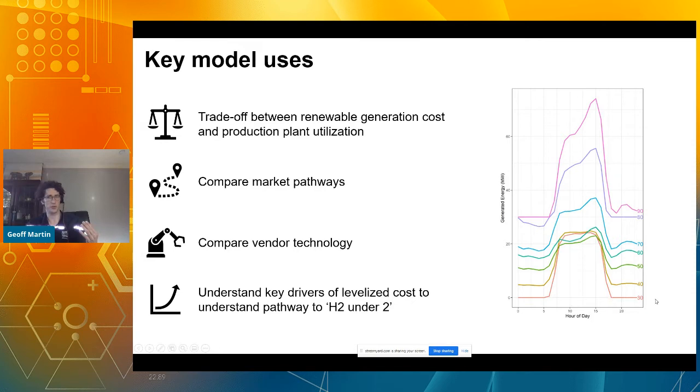So that's just where we've got solar generating our energy. And I've averaged over all the days, so you can see the average profile. Obviously, you're only going to get solar energy during the day. So most of the time, the electrolyzers are going to sit idle, so we're only getting 30% utilization. And then if you turn on some wind, wind, particularly in this location, is complementary. It particularly generates energy at night. So it's a good complement for solar energy, which obviously only produces during the day.